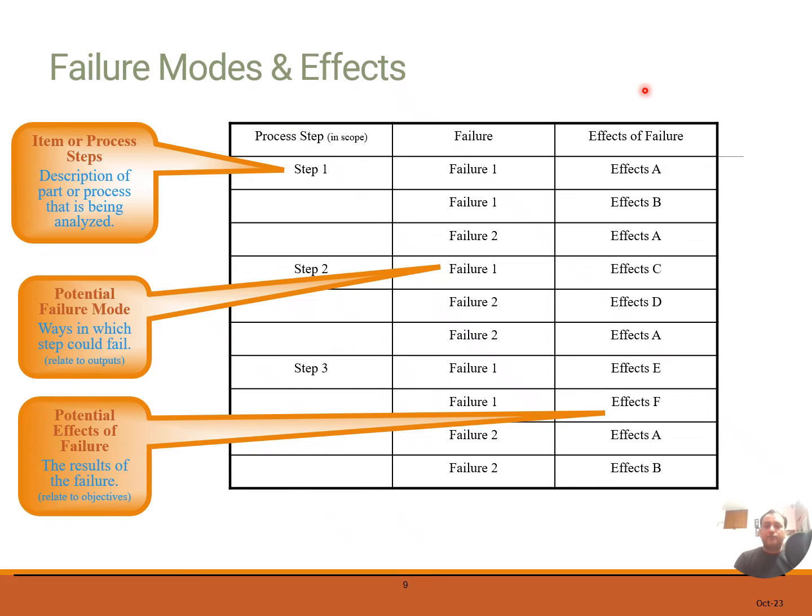The effect of not using deionized water in the rinse system, like I said earlier in the example, would be plating or sputter adhesion problems. It means it will not meet the customer's requirements. Remember, the customer may be anyone: an operator, the next process operation, an assembly plant, a distributor, and the end user itself.